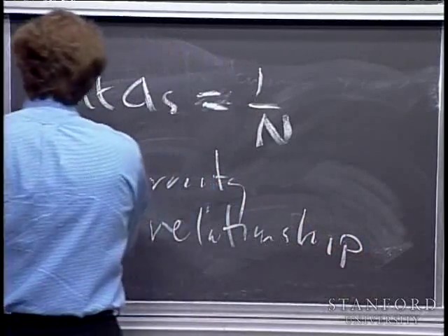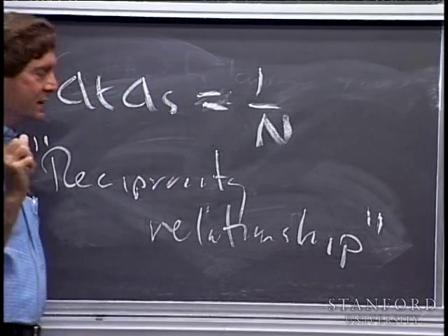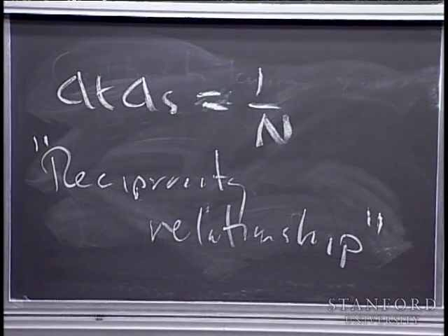Now, this again has practical significance and practical consequences when you're applying the DFT. You can imagine you have a continuous signal, you want to sample it. What can you choose and what is forced upon you?